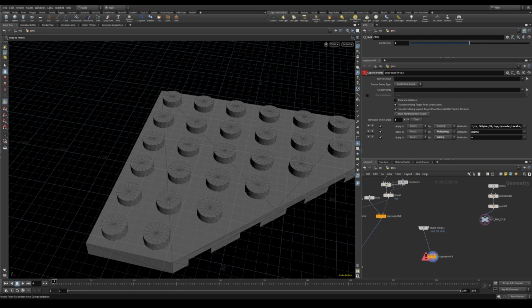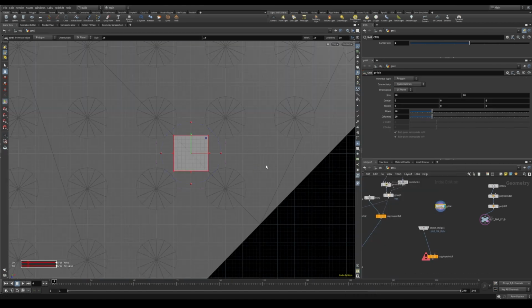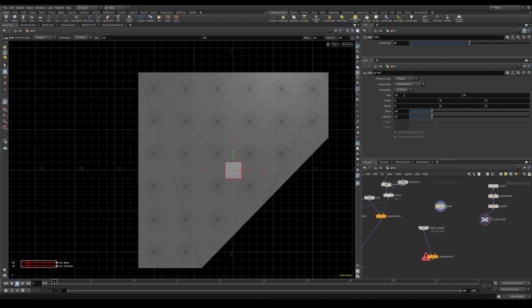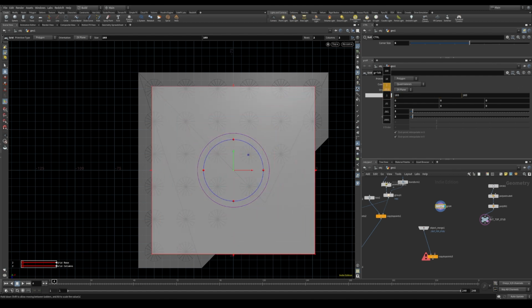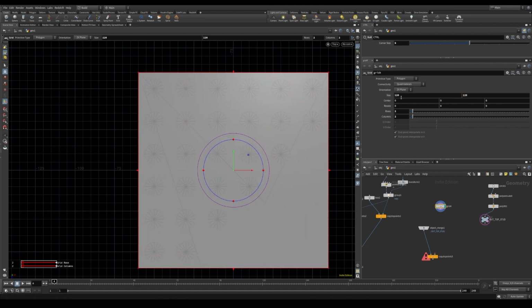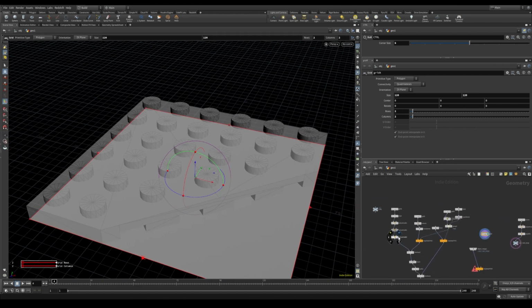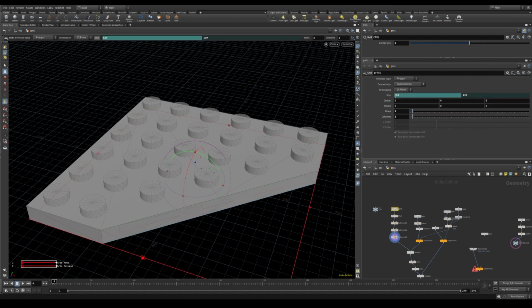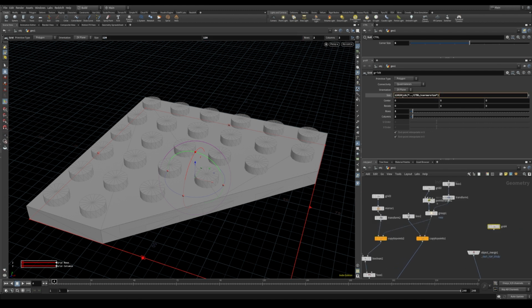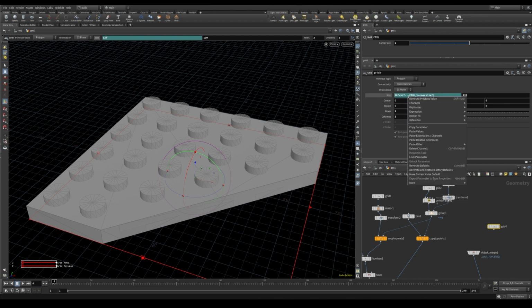Now to scatter the pieces, let's take another grid, and right now we are seeing the 6x6 variant. So let's put the columns to 2 and 2 and increase the sides until we match it, and it's 120, which is the same size of the body grid. So basically for the sides, we can use the same expression here. So let's copy it on the new grid, and let's also copy this parameter to this other one.